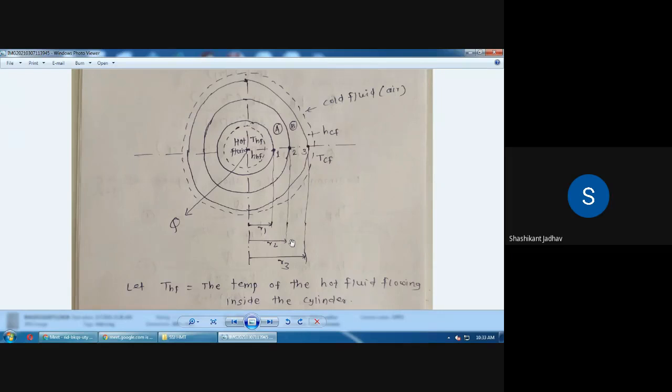So by using that equation, can anyone tell me what is the equation for the layer A? Heat transfer through that particular layer A, only layer A. Layer A मधून किती हीट ट्रान्सफर होणार आहे त्याचं इक्वेशन आपल्याला पाहिजे. Anyone tell me that? कोण सांगतंय, मदन. सिंपल आहे. मागचं जे इक्वेशन आहे ते आपल्याला आपलं पहिलं जे आताचं डेरिवेशन झालेलं आहे, Q इज इक्वल टू 2 पाय KL इंटू T1 minus T2 divided by ln of R2 by R1. So in that manner we have to write down the equation for the layer A. Can anyone tell me that answer?